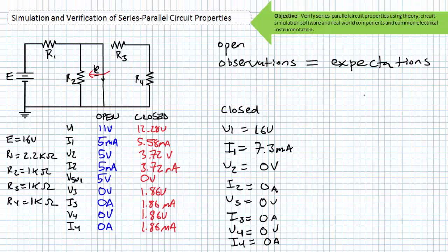Before you even think about busting out an ammeter, a voltmeter, or doing another calculation, again, take half a millisecond to look at your circuit to see if it's connected properly. Shorts are often visually identifiable with a misplaced component, a misplaced wire, an errant or extra wire, or improper use of a protoboard. Too much current will flow through a path with a short in it. No current will flow in a path with an open in it.